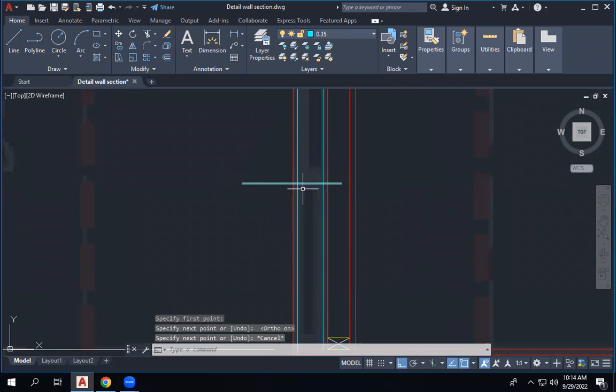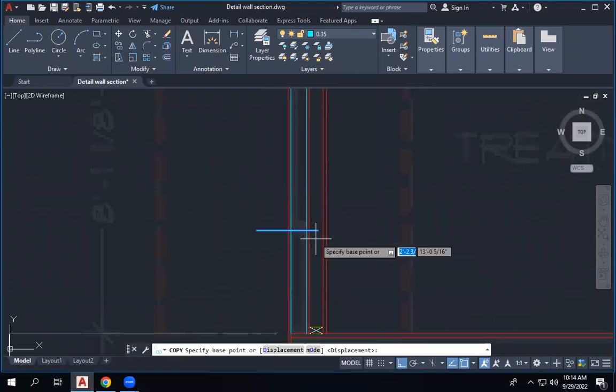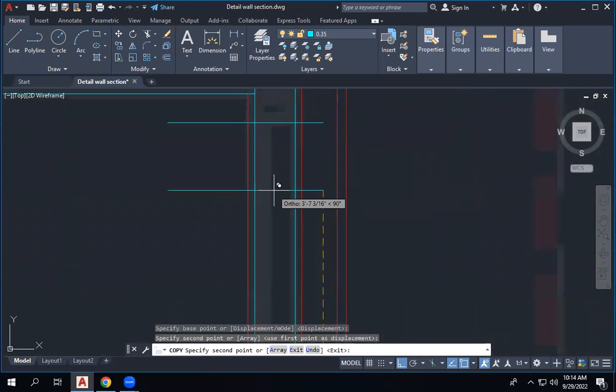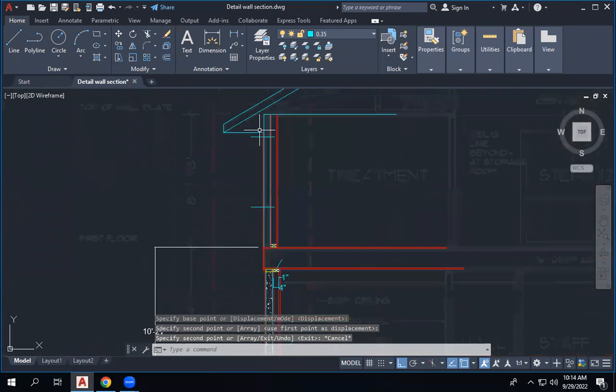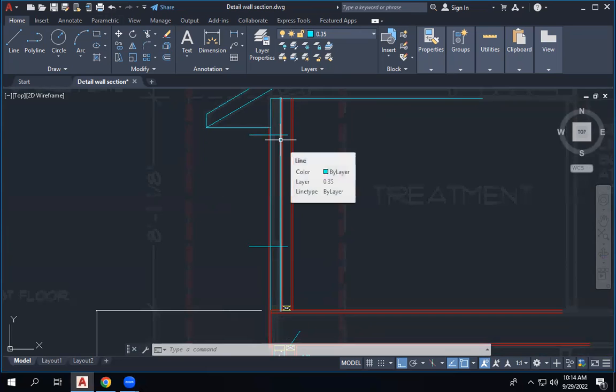What I'm trying to do is, we need to first stop our wall at this point, and I'll consider this as the window. See the image, we have the window right up to this point. So I just drew two horizontal lines. Our window will be located here at this point. What I'm going to do is trim this wall line and have a thinner line, because in the section, as I told you before, this portion and this portion will be sectioned, and these lines will be in projection.